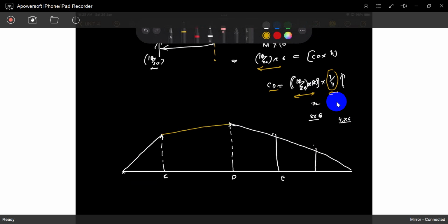But you can write down the diagram directly. How can you say directly? The bending moment at the location of Q dash, you can directly write down. So how can you write it down? Exactly, if you see, it will come like this. This is Q dash. So what is this value? This value is x into L minus x by L. What is this x? This is 6, this is 14. Divide by 20, 1 by 4.